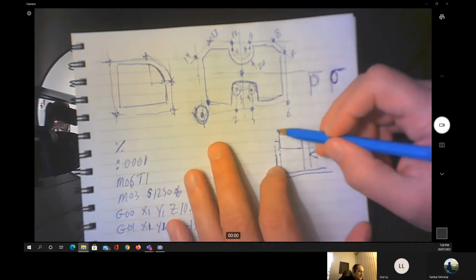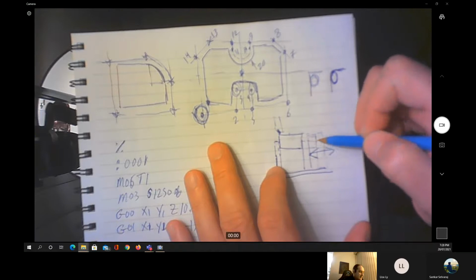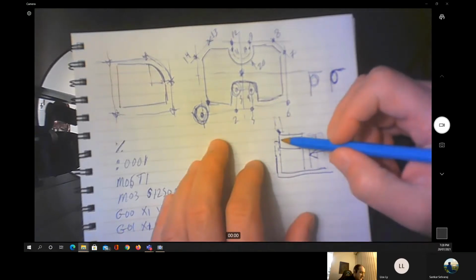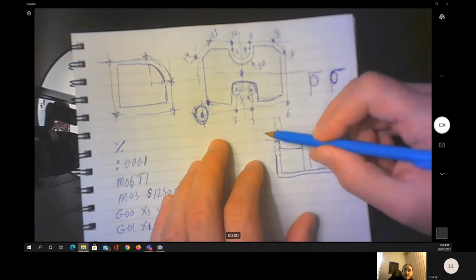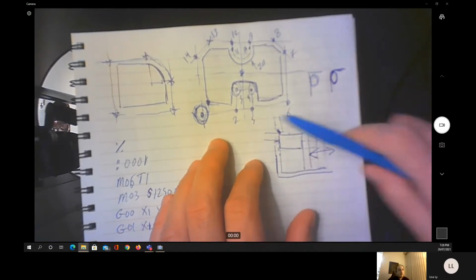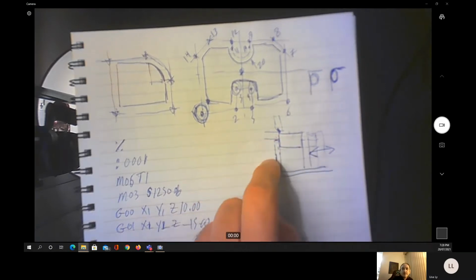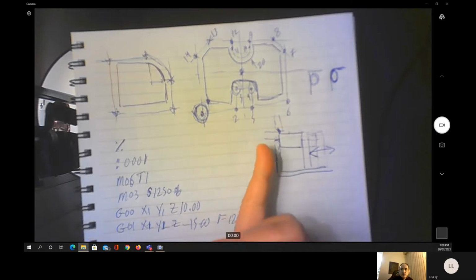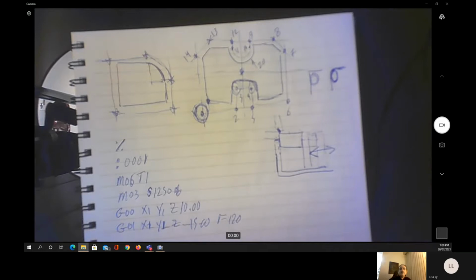So that's why we always prefer to have the datum point here, and the cutting tool will always understand that we're not going to hit the jaw of the vise while we do the work, and we always have to be careful that we're not going to go deeper than this area to hit the jaw. So this was the main reason why we need to select the datum point at this position. We always put it on the side of the fixed jaw of the vise, and this allows us to use the same setup for multiple parts.